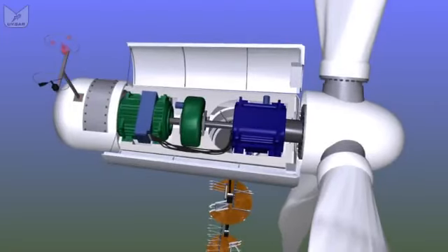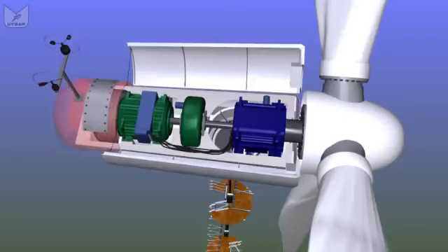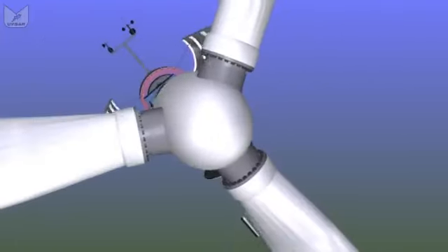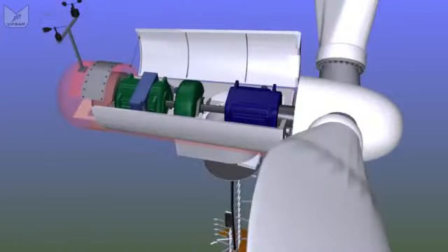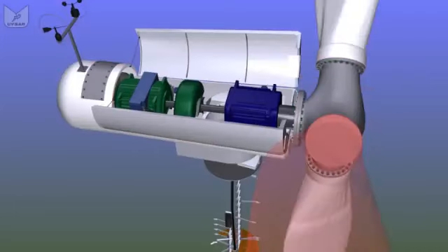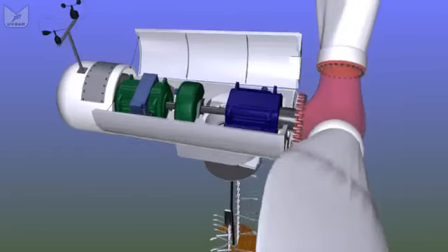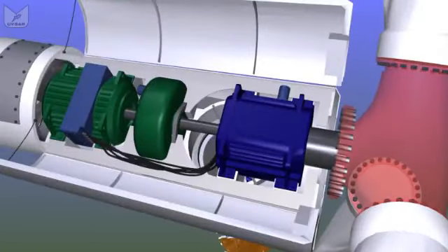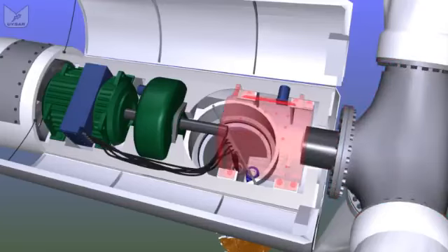At the back we have the wind sensors, which give us speed and direction and allow the turbine to face into the wind and to change the angle of the blades. The nacelle itself is just a fiberglass tube. At the front we have a similar fiberglass cowl protecting the hub, which is a steel casting on which we have bolted our 3 blades, and the blades can turn or pitch so that the angle they form with the wind can be varied.